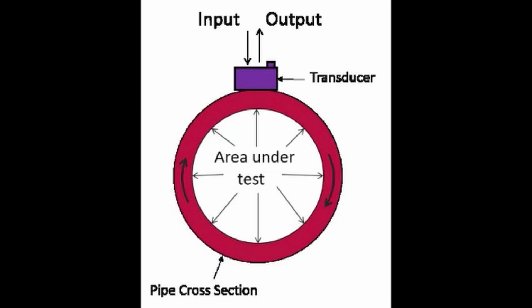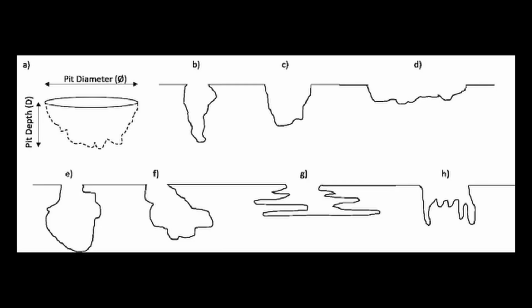A cross-section through the pipe where the transducer is connected to the top of the pipe, and an analytical wave travels around the circumference of the pipe. If corrosion is detected, the frequency of the wave changes appropriately. The diagram illustrates the outcome results compiled from 8 cross-section locations in the clockwise direction of the pipe under investigation. The corrosion detected in the walls of the pipe.